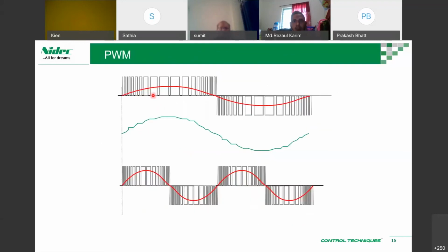So this is the output of, let's say, 20 hertz. Then you get this form. Just to compare, you get this current output. This is your voltage output, and this is your current output. As I said, you may have some spikes and so on, so it's not clean. It's not always a true sine wave. You get a simulated sine wave. This is what the motor will get, and it can make the motion.